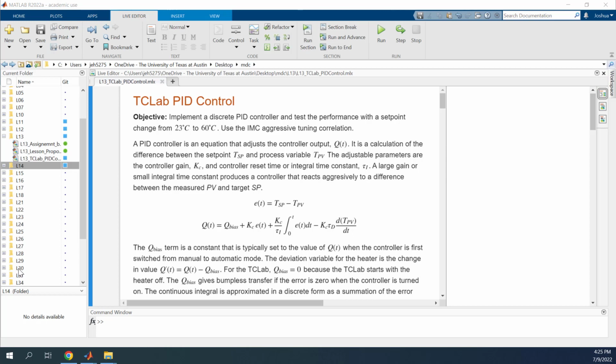Integral control is good for non-integrating processes such as our temperature, such as the speed of a car, such as the concentration coming out of a CSTR, processes that aren't integrating, because the integral control will counteract that persistent offset. The problem of integral control, though, is that it can lead to oscillations, and so derivative control seeks to minimize those oscillations that usually happen because of large changes, large derivatives in the error.